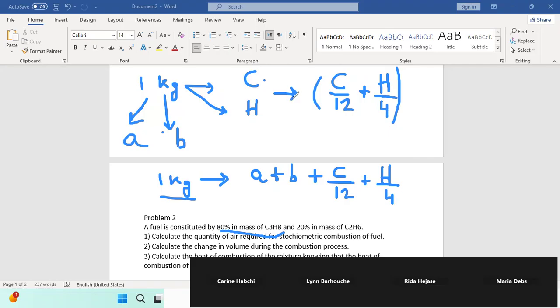For CO2, we know that the number of kilomoles of CO2 formed can be found from the chemical reactions. So we have two chemical reactions. We can determine the number of kilomoles of CO2 in products and the number of kilomoles of H2O in products, and then we take the difference. If you do the two methods, you'll obtain exactly the same result. You can try the two methods and make sure that they give you the same values for delta.